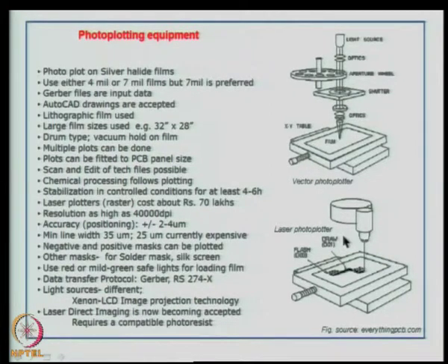Whereas, in a laser vector photo plotter, as you can see here, here also there is a light source. Okay. Now, basically because of the raster format, irrespective of the D codes, they move very fast and the apertures are open very fast, and basically you are not looking at sequential operation, you are looking at the complete film, and the laser source is so sharp that you can do this entire operation much faster than the vector.